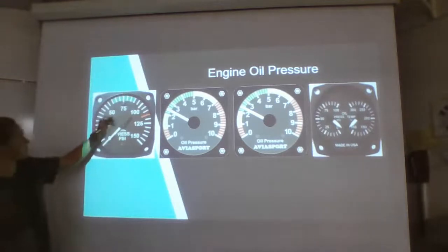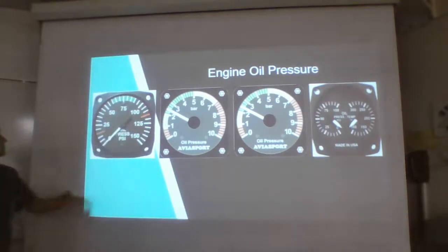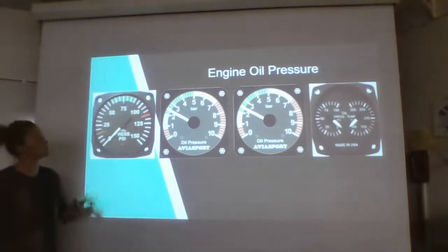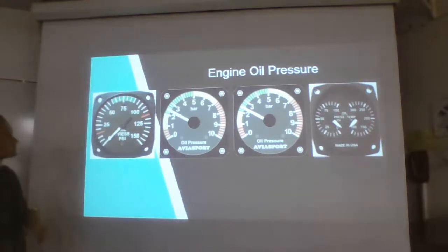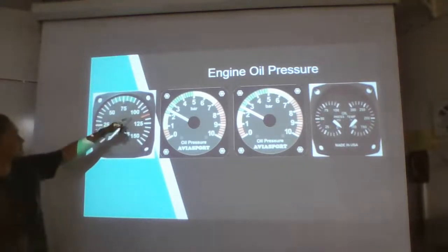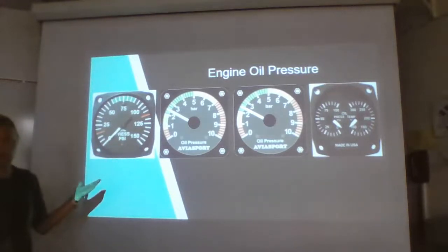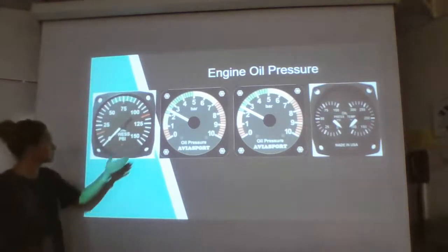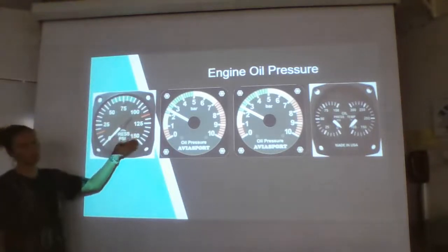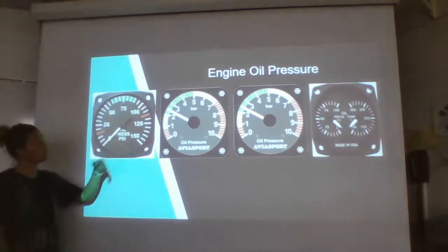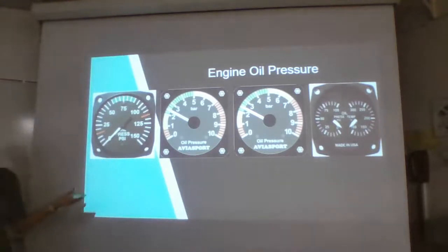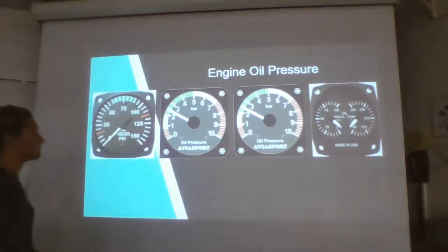So no caution area, but pilots that are familiar with these things, they know those numbers. And same with us, we need to know that these numbers are correct. And what we would do with any gauges is if a marking is not legible, we need to know where that marking should be and that it's legible for the pilots flying these planes. So if that isn't legible, we need to know to annotate that and get that corrected or changed.